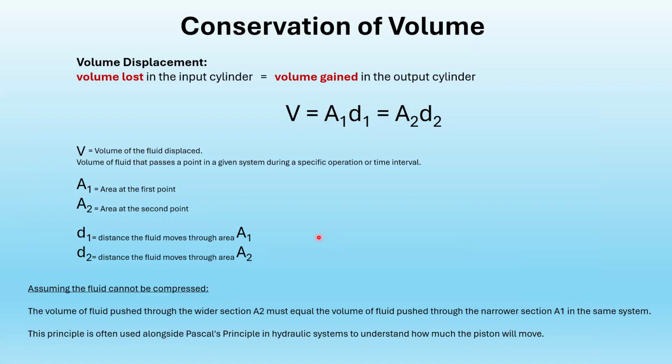Hydraulics uses fluids, mostly oil. It can be water, yes it can, but we're dealing with mostly oil, and that, in comparison to pneumatics, the medium that is in those pipes that we're moving is considered incompressible. So we have more control with hydraulics as far as the distance displaced and the equality of speeds, I would say.